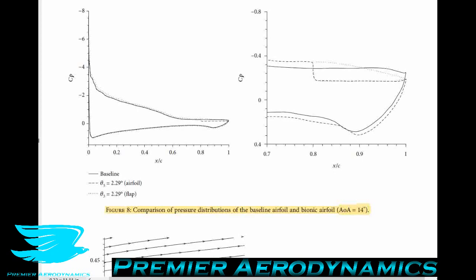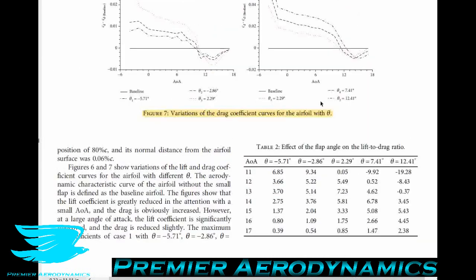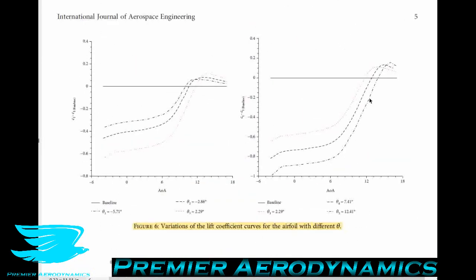So that means that the adverse pressure gradient is lower. If the adverse pressure gradient is lower, it means that the flow can stay attached to higher angles of attack, which is why we delay stall. And that's what's happening with this flap. And while it may seem like an interesting result, it isn't really that surprising, because anytime you mess with the trailing edge of an airfoil, you're probably going to affect the adverse pressure gradient, and that affects the stall characteristics as well.